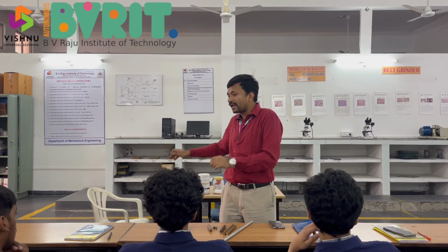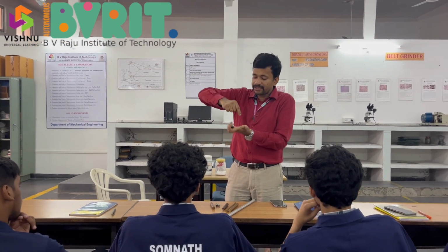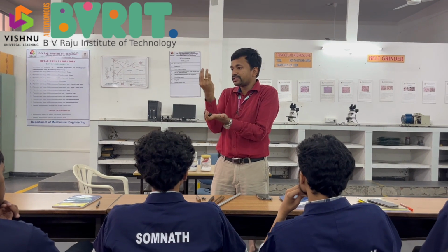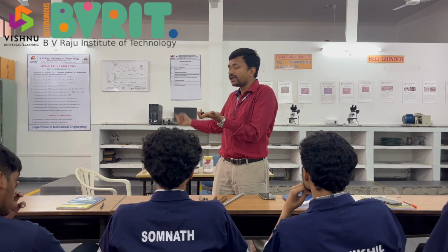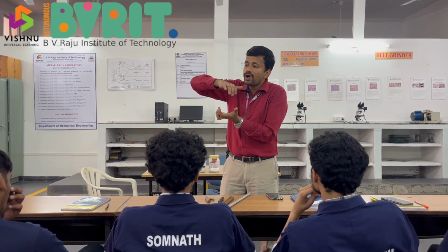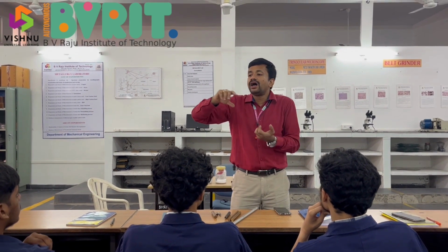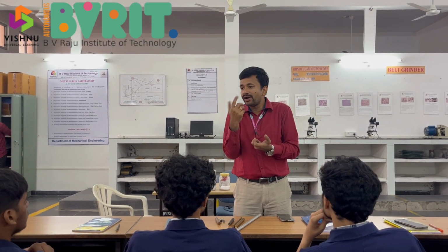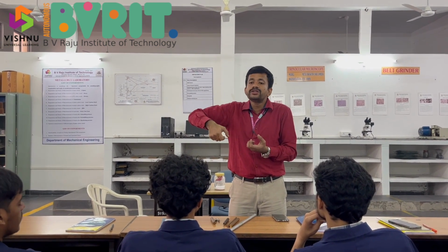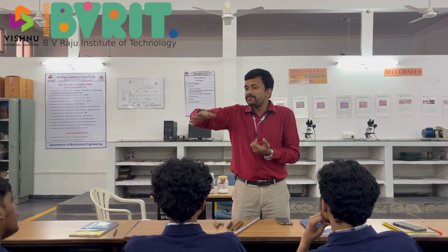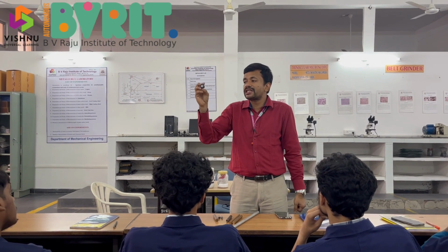So you have a bakelite powder, and first of all you need to place this specimen at the bottom, where there is a container. In that container you place this, then you pour the bakelite powder and compact it and apply a temperature over it. There is a heating coil around it, and also a hydraulic press with which you can compact it. It will take roughly 20 minutes or so to get the required strength,